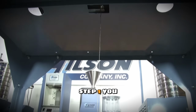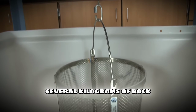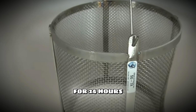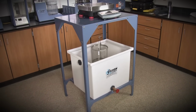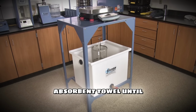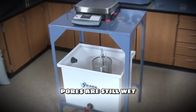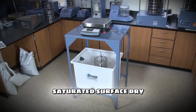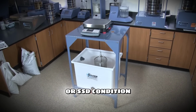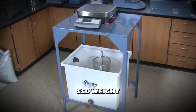Step 1. You take your coarse aggregate sample, which can be several kilograms of rock, and you soak it in water for 24 hours to fill all the internal pores. Step 2. You take the rocks out and roll them in a large absorbent towel until the surface is dry, but the inside pores are still wet. This is called saturated surface dry, or SSD condition. You weigh the rocks right there on the bench to get your SSD weight.